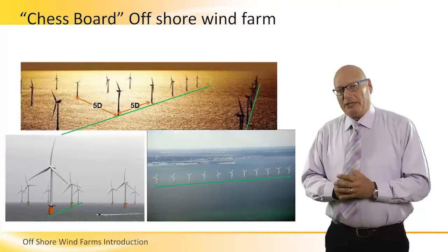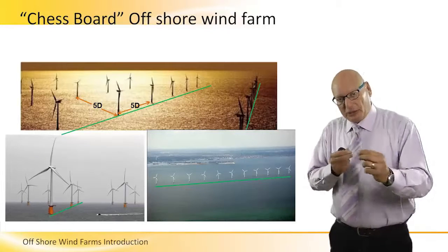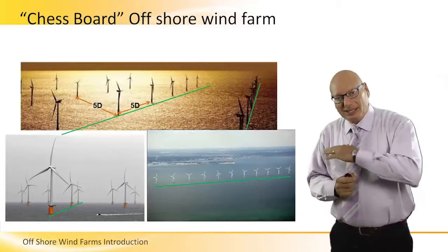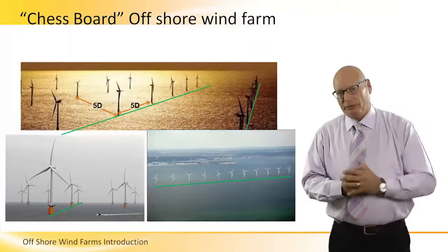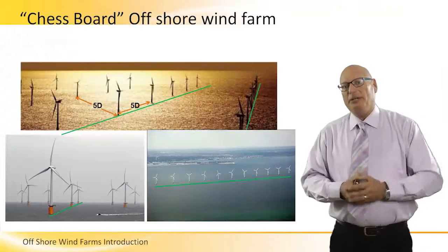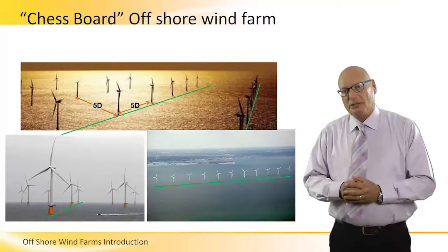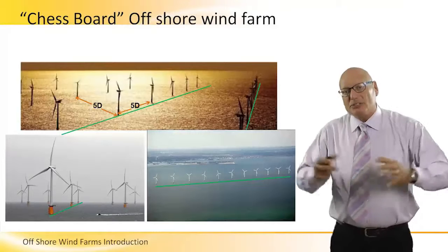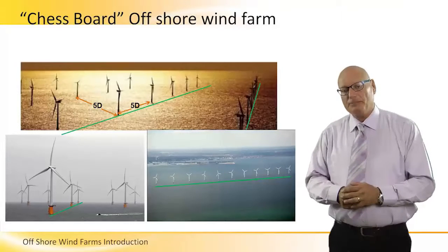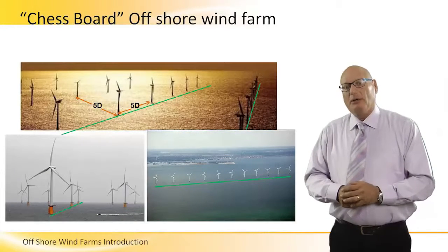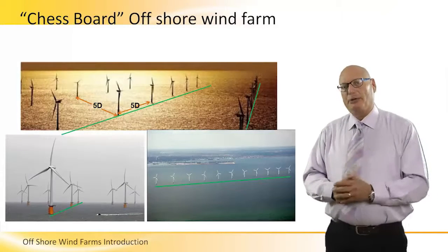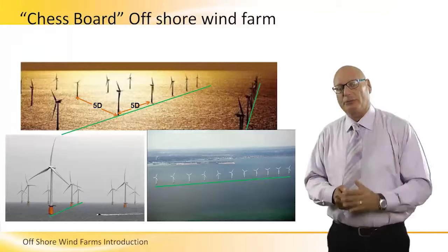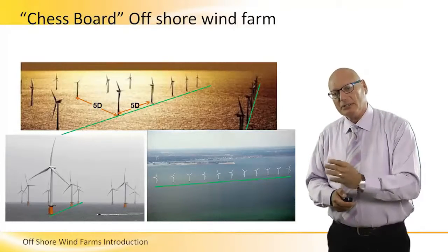The drawback of that, because of the long distance of one turbine to another, means that the entire area of the park will be very large, meaning that there will be longer cables, meaning that the substation will be far away from several turbines in the farm. But from a technical point of view, it's easier to draw straight lines and to run with turbines along it. But it has its drawback.